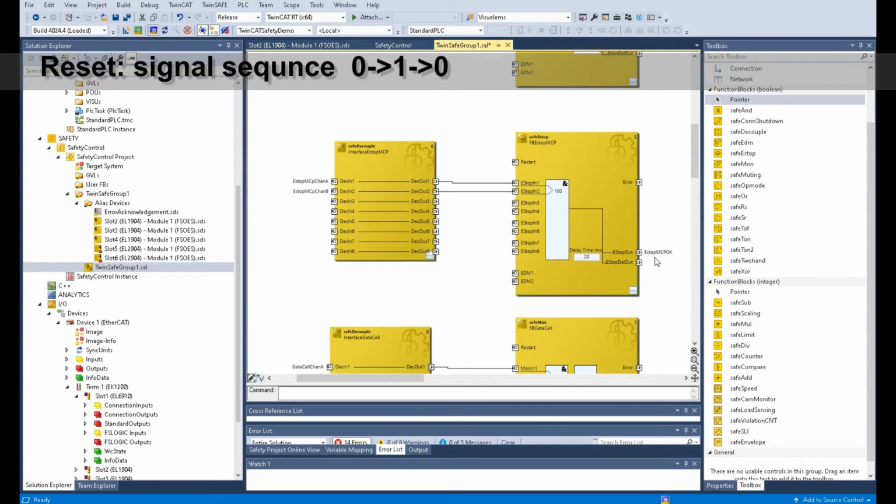And after the EStop button is released, both channels will turn on. But at that time, without this restart signal, we want this output to still be 0 in safe state rather than go back to on automatically. If these 2 channels are already on, and after we give a reset signal, our output will turn on from 0 to on, recovered.